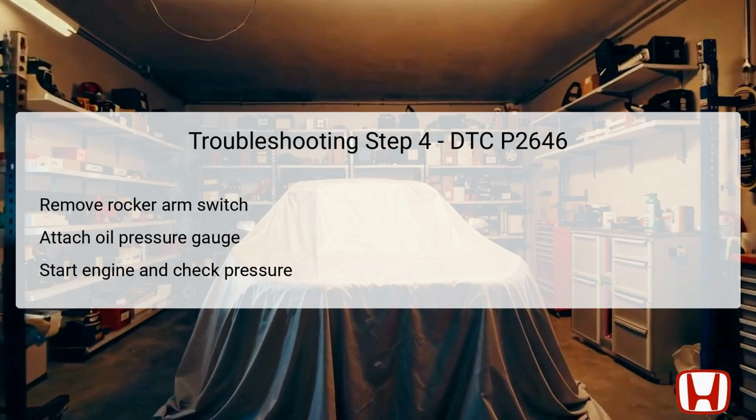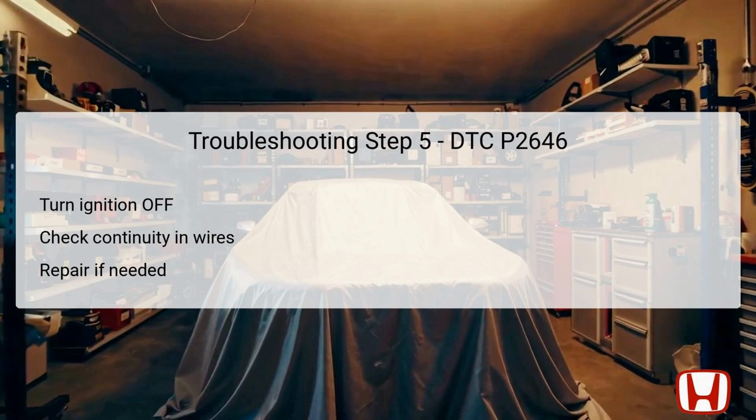The final troubleshooting step focuses on verifying the integrity of the wiring within the VTM line to locate possible shorts. Start by turning the vehicle ignition to off mode to ensure all circuits are safe to work with. Using the Honda Diagnostics System, or HDS, jump the SCS line and allow it to sit for over a minute. Disconnect the PCM connector B, which houses multiple pins, and check for specific continuity between designated test points. No. 21 on the PCM connector and body ground.